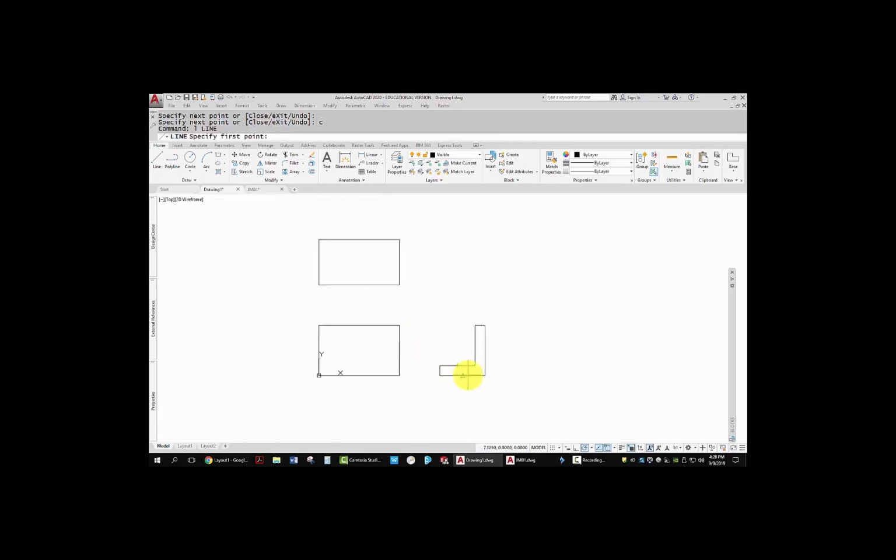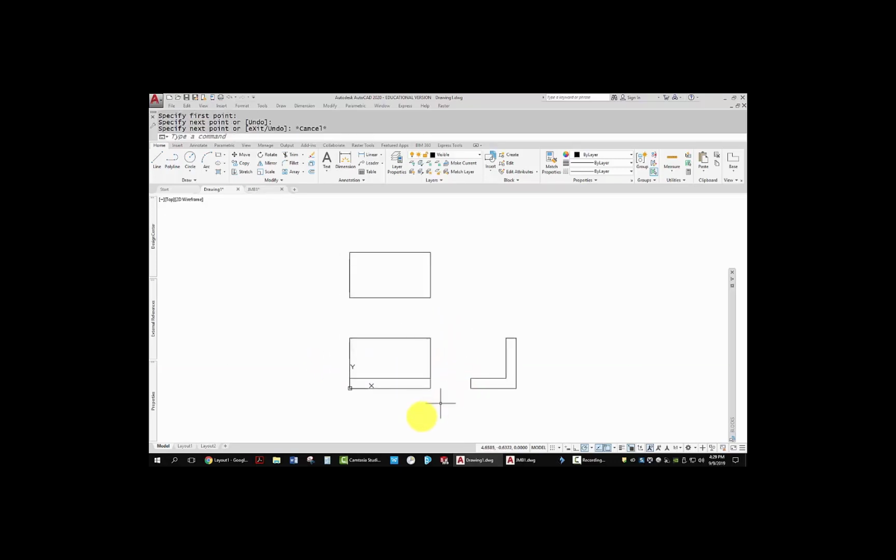The line across the front, that lines right up with that corner. I'm going to hover over the corner, come across till I get an intersection. You notice I'm not getting an intersection because I don't have it turned on in my object snaps. If I go to the object snap dialog box, intersection is right there. It is turned on, so that's not the problem. But sometimes by just looking at your object snaps and coming back out, problems in AutoCAD will go away. Let's find out if that's true. Highlight corner, and it's true. Intersection, left click, intersection. Now I have those two lines.